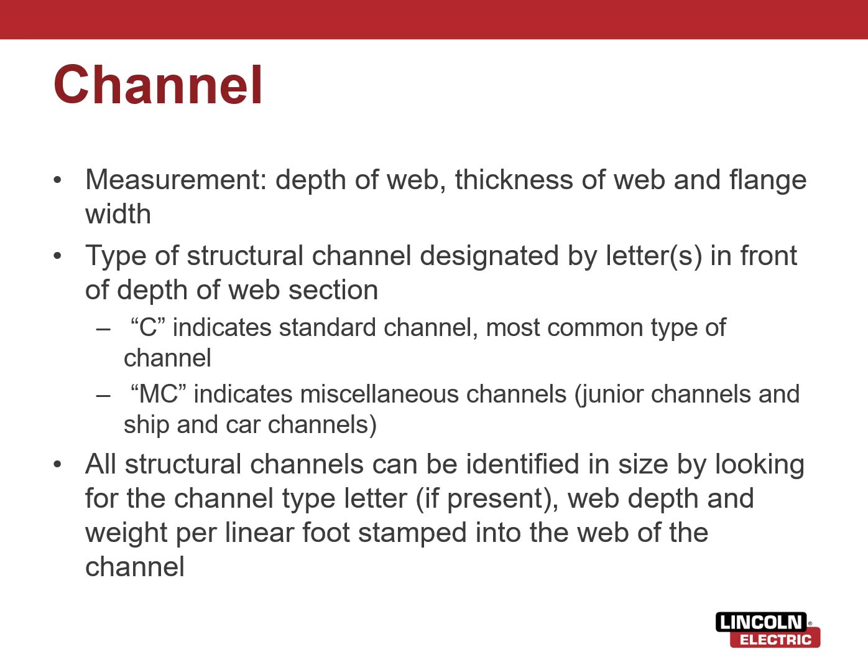So again, the measurement would be depth of web, thickness of web, and flange width. All right. This type of structural channel is designated by letters in front of depth. So C indicates standard channel. It's the most common type. And then MC indicates miscellaneous channel. So junior channels and ship and car channels, so just different styles. So it's still a C channel, but it's going to have different measurement profiles.